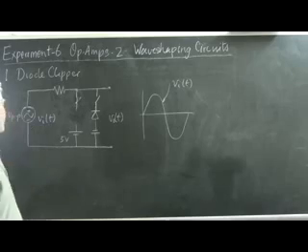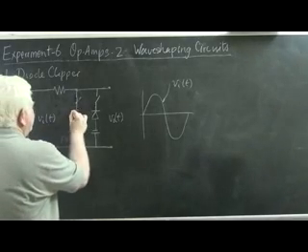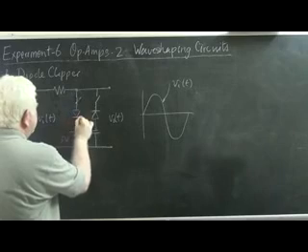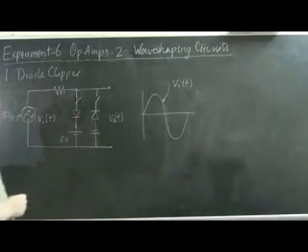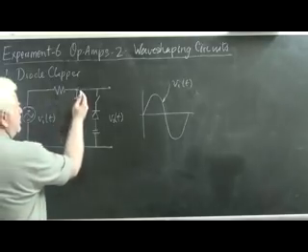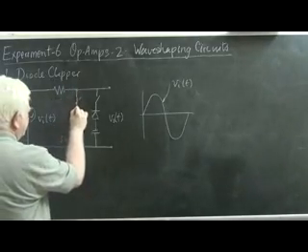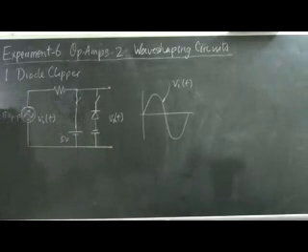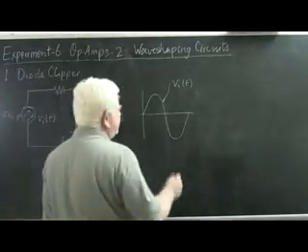So when this input voltage exceeds the battery voltage plus the cut-in voltage, then this diode acts as a short. So what you would see instead of the diode here is this, which simply means that the voltage across the output terminals is 5 volts.